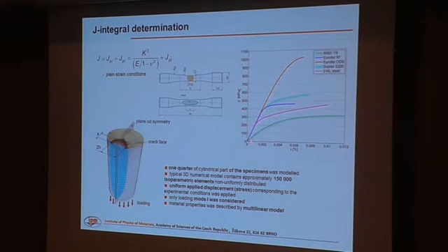The highest stress strain curve corresponds to this Eurofer ODS steel, and for example, in comparison with the Eurofer steel, which has the same composition, but without the yttrium oxide, you can see that you obtain approximately twice the cyclic yield stress, for example. So you can see that these materials are really different from each other.